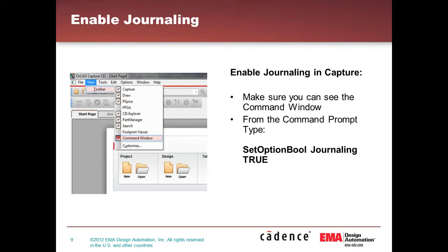The command set allows users to perform a large set of operations automatically for specific needs and offers a ton of customization capabilities. One last important note regarding support for journaling within Capture is that it also helps in debugging custom scripts, as it provides a definite mechanism for step-by-step recreation that will allow you to identify any issues with your scripts.